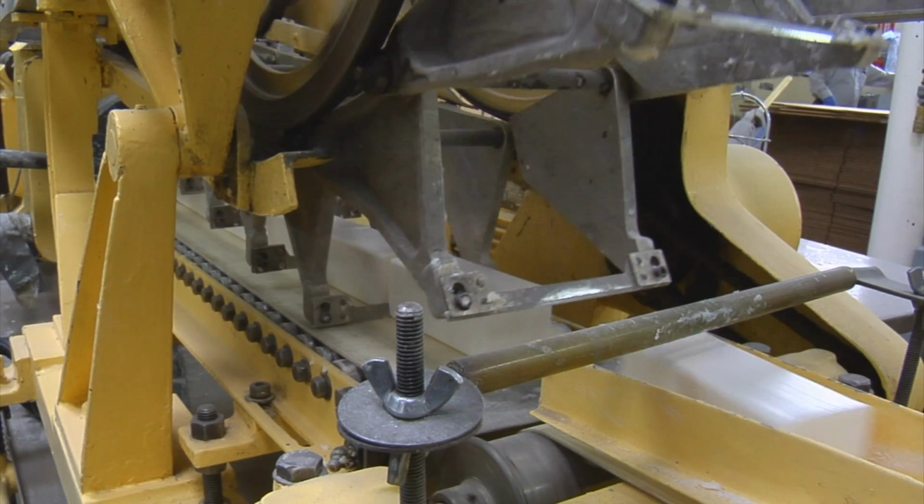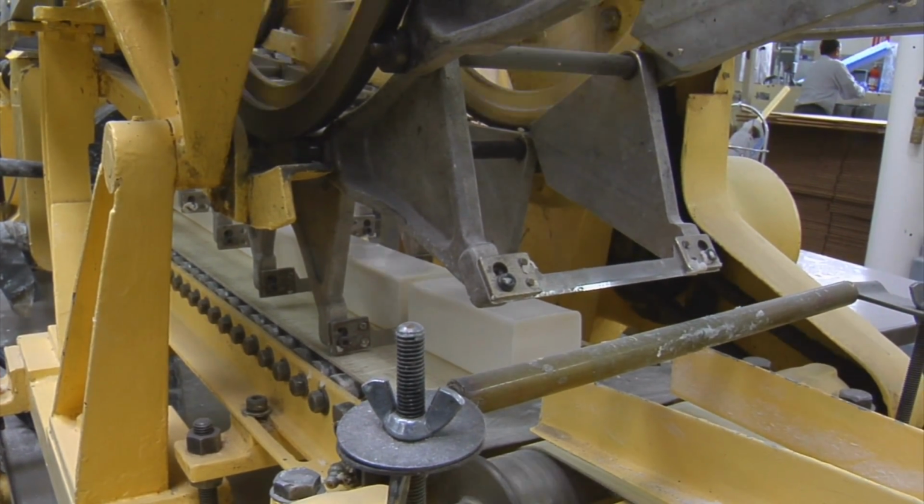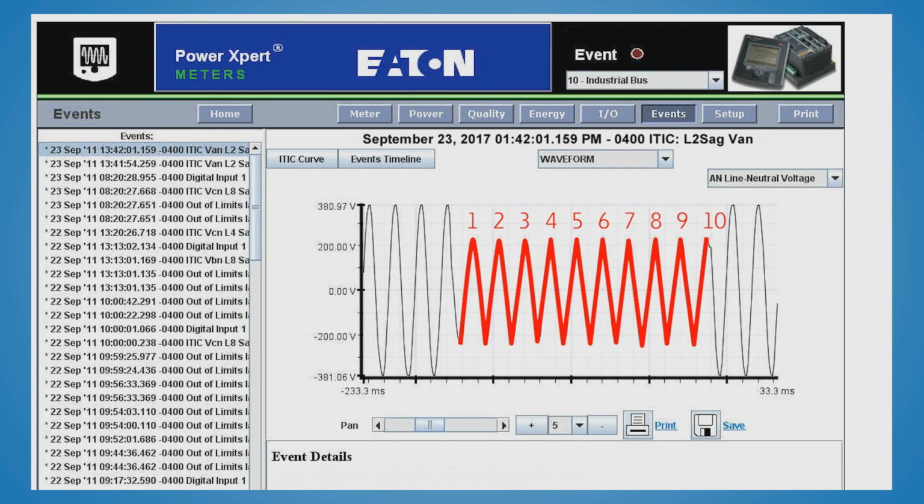Voltage sags are considered the most costly power quality event and the most common voltage variation, much more frequent than full interruptions on a typical power system. We've had many visitors tell us that they've lost hundreds of thousands, even millions of dollars as a result of voltage sags. When evaluating voltage sag issues, identify the magnitude of the retained voltage, the duration of the event, and the number of phases affected for historical data at the site.